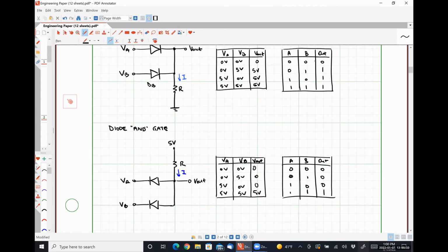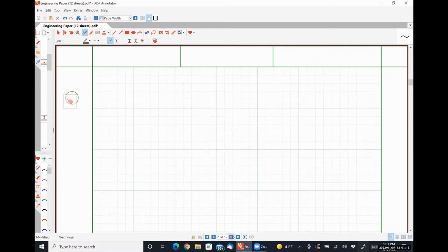By too much, right? So we know that for a real gate, we're not expecting the output voltage to exactly be 5 volts. We're expecting it to be above some threshold, which we call high, and below some threshold that we call low. Well, if we put too many stages together, the forward bias drop over the diodes will be enough to push a high signal into the range interpreted as low. So best case scenario, we can really only get 2 stages out of a diode-based logic circuit before we need to have some form of amplification involved. And the amplification comes from transistors. So with that being said, let's start talking about transistors.